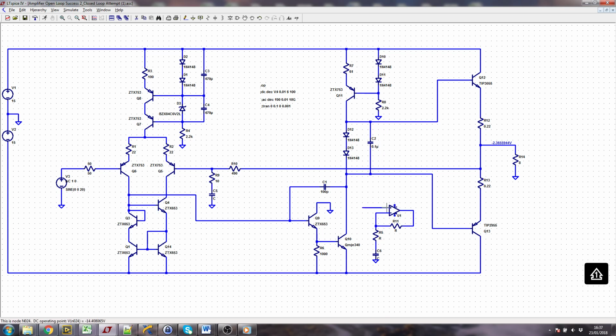So this is effectively my V plus, which is here. This is my V minus, which is here. R11 is R10, R5 is R9, C6 is C5. If I get rid of that and run that straight to ground and ask you for the gain, you'll say, 1 plus R11 over R5. Great, 1 plus R10 over R9.